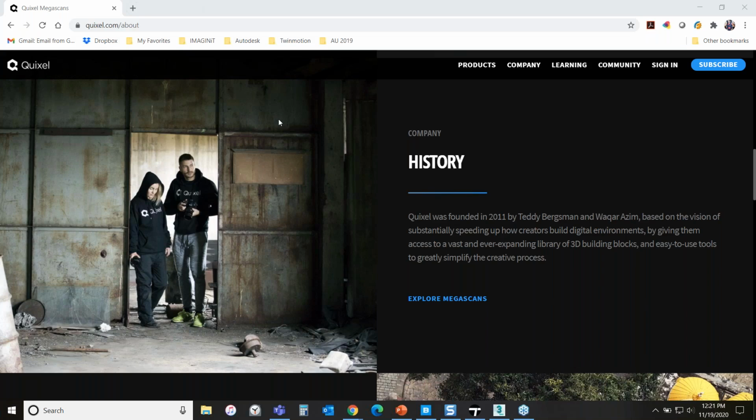So one thing we want to communicate to everyone is that with this process, yes, we can use a point cloud to create that really enriched 3D model that's accurate and is capturing that real situation. And I know a big theme of AU this year is this idea of a digital twin. When we do a ground-up design in construction, we might do the model in Revit, but once the building is built, we don't really have anything to verify that it was constructed the exact same way that we designed it. So having a point cloud and reality capture techniques, we can actually start to produce an accurate 3D model to the as-built, real-world condition, which is a really important theme. And we actually have a presentation later today which covers that and how it relates to facility management and digital twins.